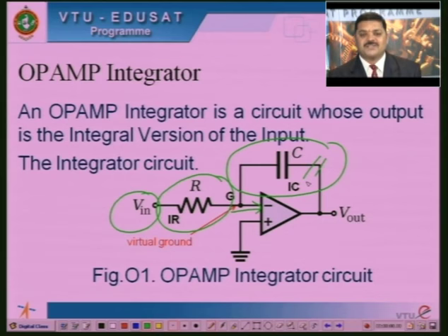If we use the capacitor, it performs integration operation. So, you can remember the integrator circuit as, consider the inverting amplifier. In an inverting amplifier, we are giving the input signal at inverting input terminal through the resistor R1, and in place of RF we will be connecting a capacitor.